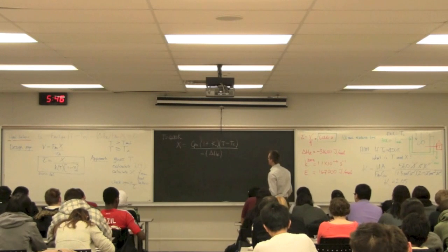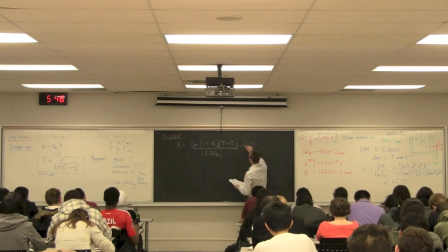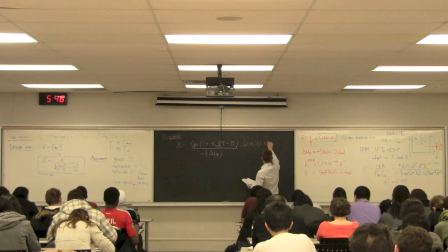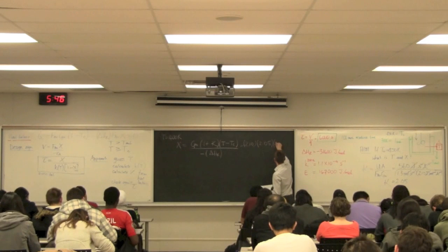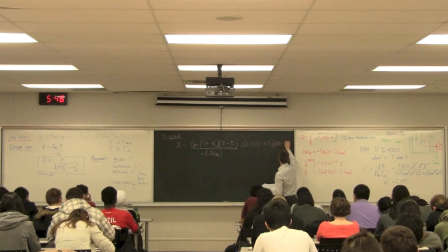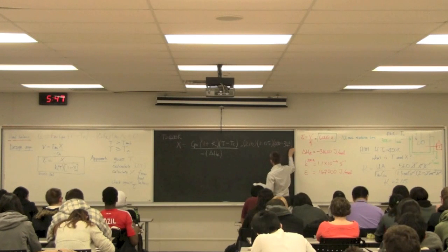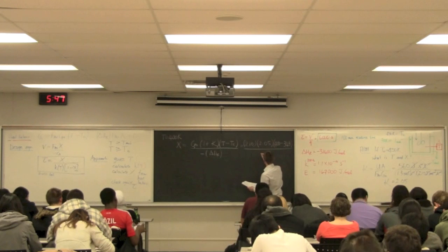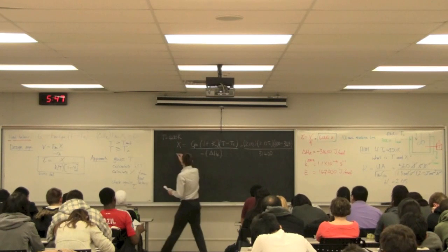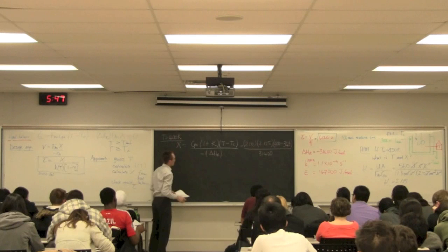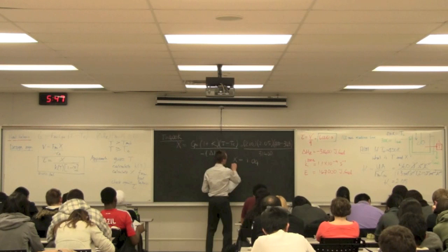So if we substitute in those values that we know, Cp was 210. I'll need you to check that the units do actually match. T, our estimated T, is 400, minus Tc, which was 349, divided then by 31400 for the heat of reaction. This is my initial guess for temperature. If I do that, I will calculate a conversion of 1.04, which is nonsensical.